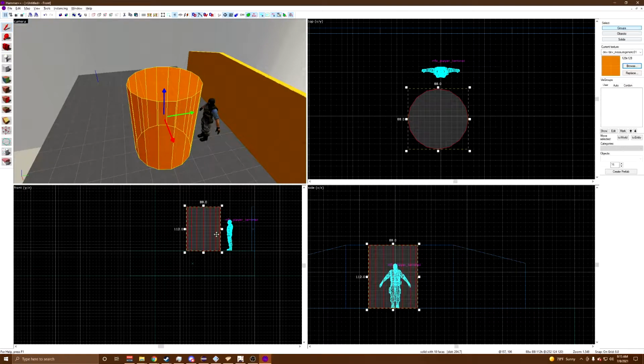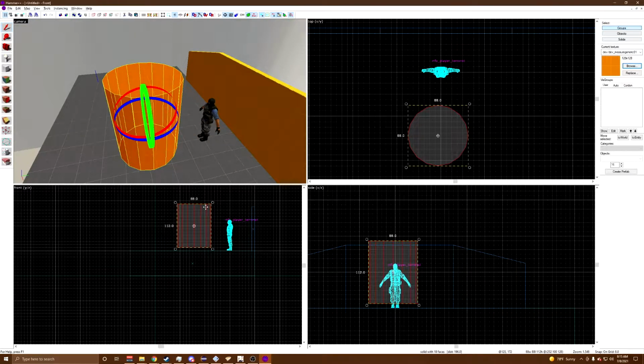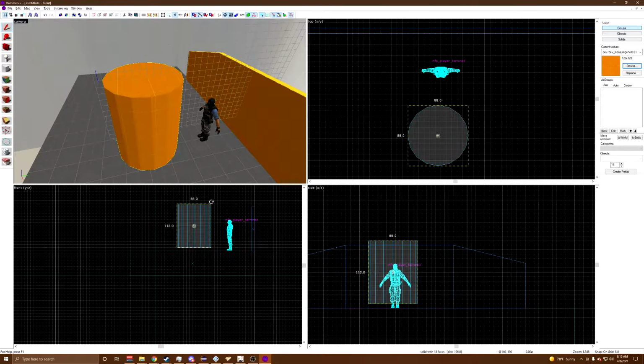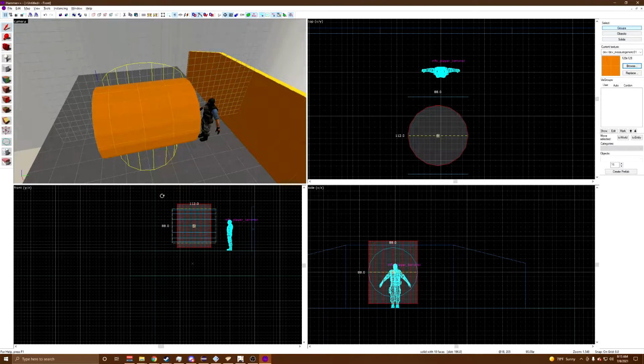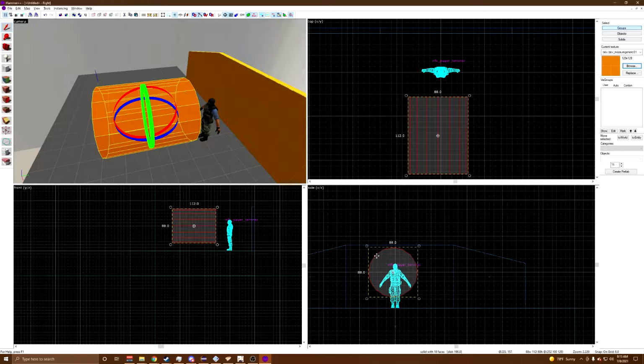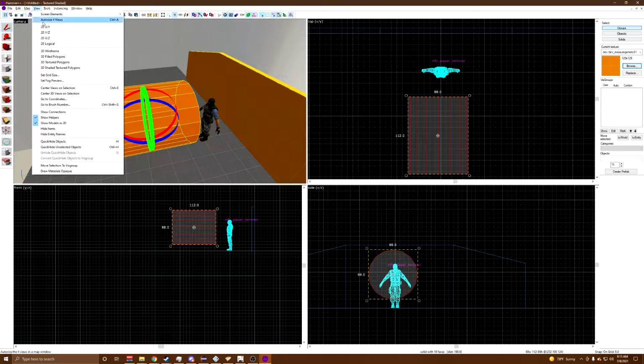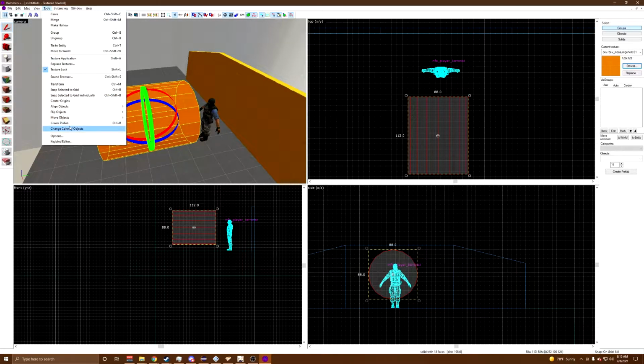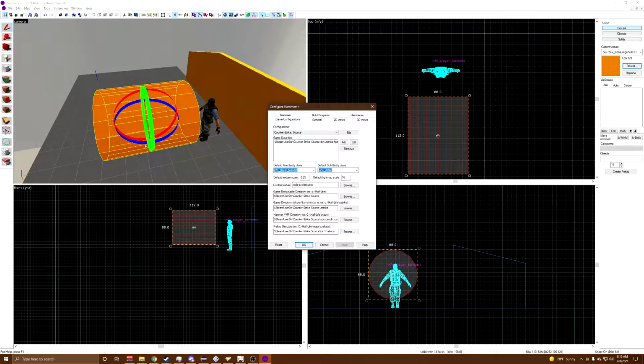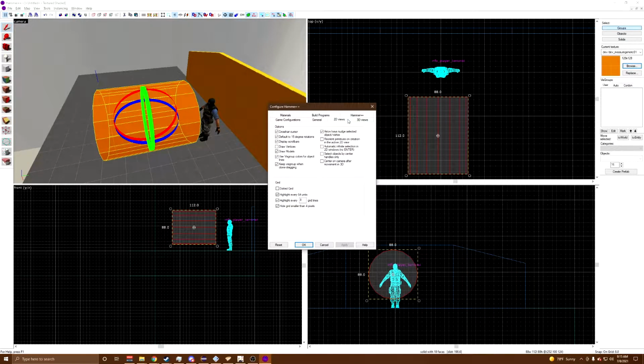You can now rotate your door to face the proper direction that you need it to. If you don't know already, you can select an object in the 3D view. Then you can cycle between resize, rotate, and shift by clicking on the object in the 2D view. 6 boxes along the perimeter is for resize, 4 circles is for rotate, and 4 boxes along the perimeter is for shift, but I never use shift, so don't worry about that one.